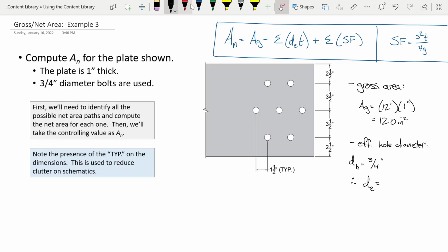If the bolt diameter is 3/4 of an inch, what's the hole diameter? 7/8. And you get that by doing what again? Remind me? Add 1/8 of an inch. So here, I'll write it out. Write my governing equations. These are system parameters, aren't they?